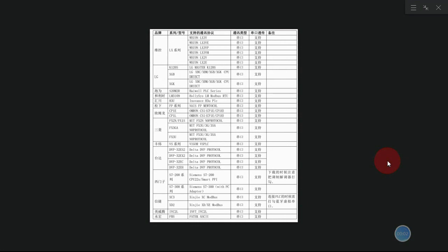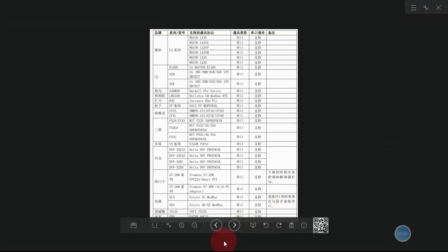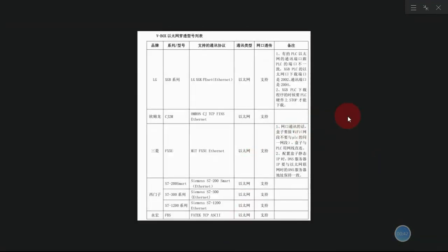So now let's go to another function, WECON VBOX Remote Download. This is very good for machine makers, or for work sites very far away that have some problem, where you need to modify the PLC program, or you just want to debug the PLC. Currently VBox supports two ways of remote download. First is the serial port. The second is the Ethernet port.